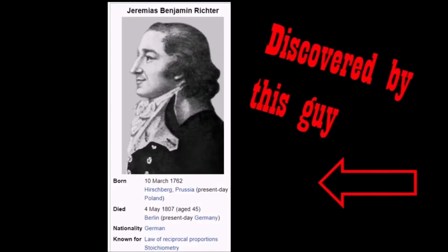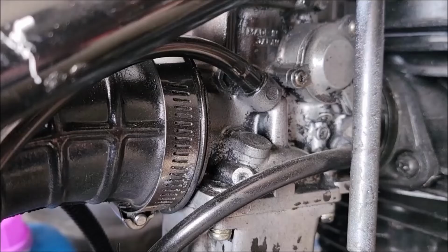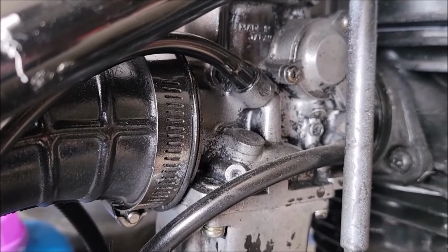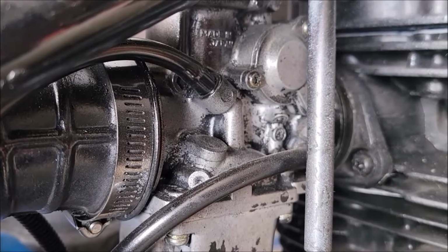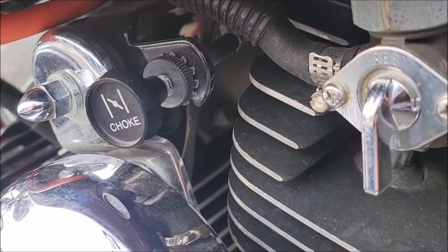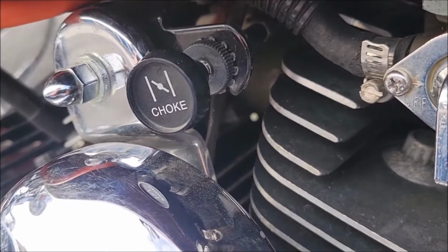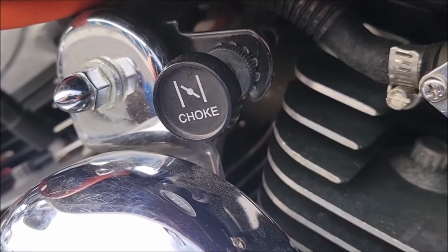However, because you change the demands of your engine constantly when you ride, your carb will need to adjust itself to get as close to this ratio as possible on the fly. If your ratio is heavy in air, it is referred to as a lean ratio. If your mixture is heavy in fuel, it is referred to as a rich ratio. Before we talk about how your carburetor adjusts itself so as not to run lean or rich, let's talk about how this air-fuel mixture takes place.